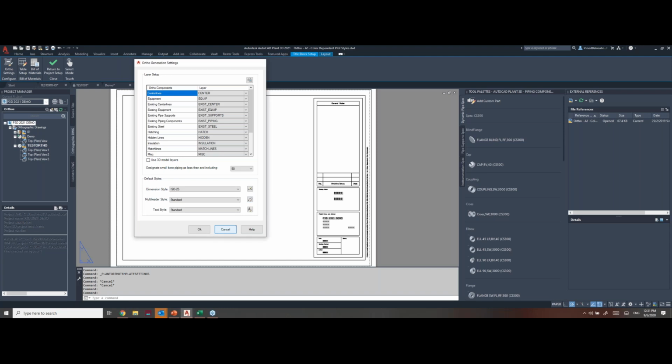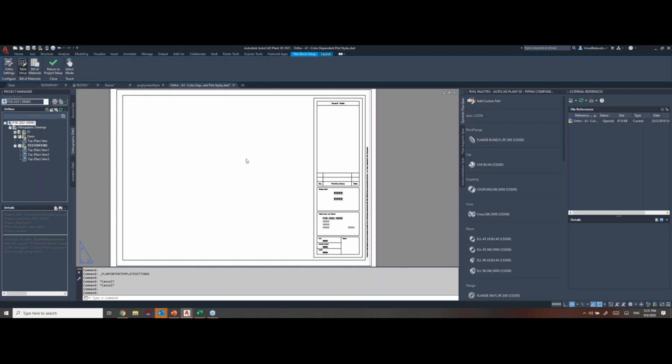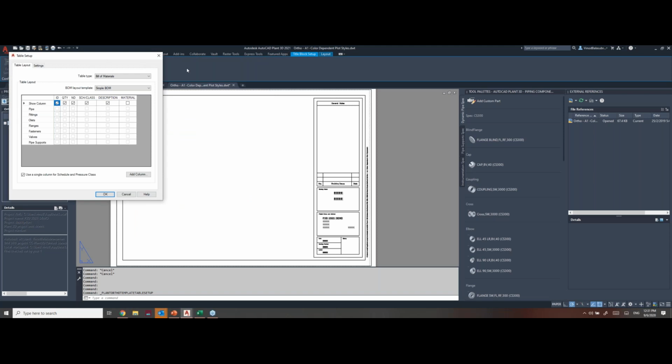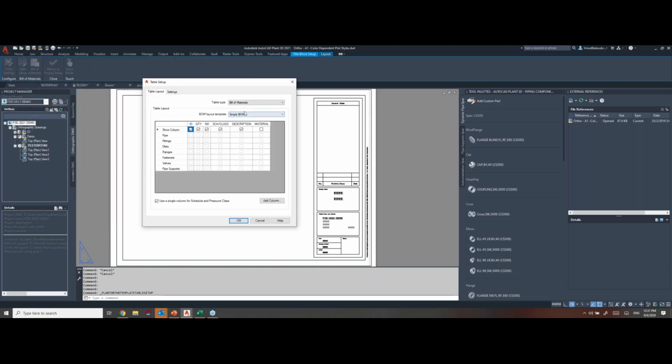And that's on the auto settings, and then we'll go into the table setup. Here you can quickly make changes around how your bill of material table needs to look. We talked about 3 different styles that are preloaded there, which is whether you want a simple BOM or a grouped one with some category titles, segmenting each of the components that you want to display. And then you can group it with independent columns as well. You can get a short preview as well, of how it looks and where you want it to change.